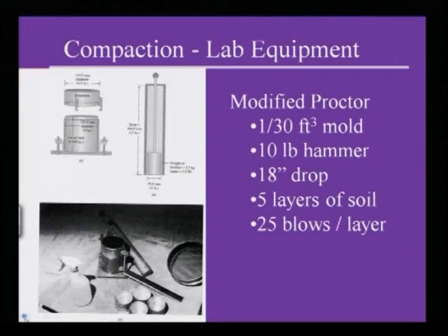Now, if I go back to the original one, as per the ASTM standard, this is the compaction mold, and this is how you do the compaction. In this compaction mold, whatever soil sample you take, you divide into 3 parts, measuring the height of the first part of the soil to be filled.